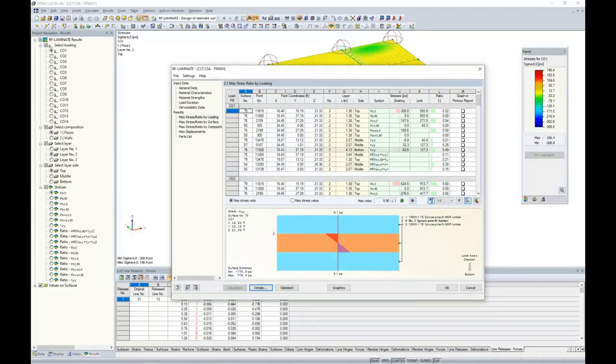So once you've applied the average regions, come in here, check on this checkbox. You can run your calculation again, and now we take a look at our max design ratios, and we see a max check now of 0.9. So that was significantly reduced from 1.81 clear down to 0.9 just by applying average regions and those FE mesh refinements, rather than increasing the thickness of our panels or decreasing loads. So that is how you essentially can deal with singularities with CLT design.